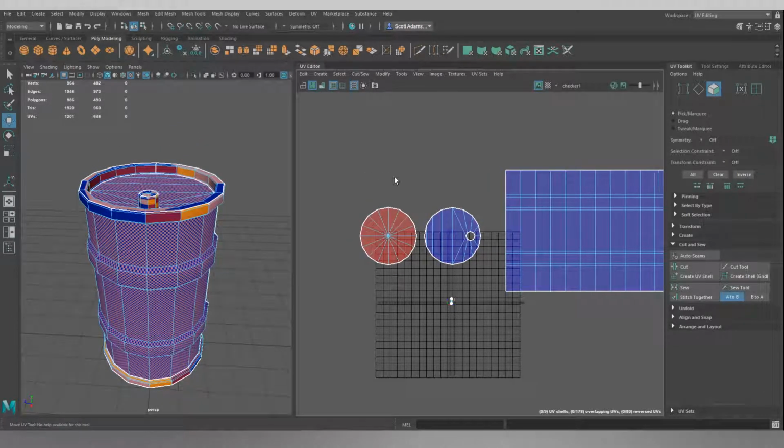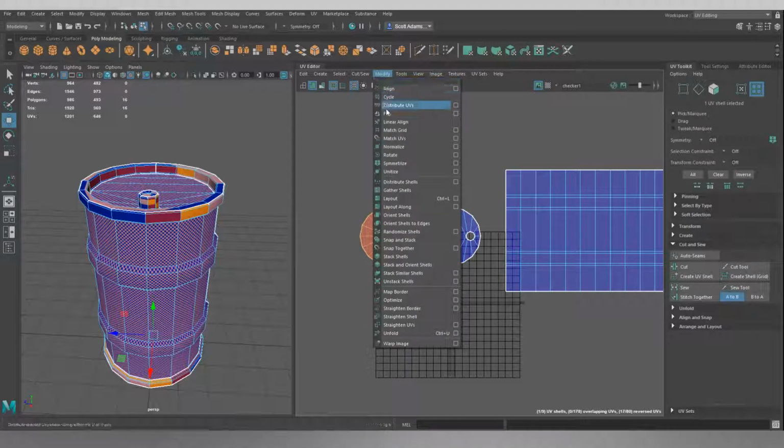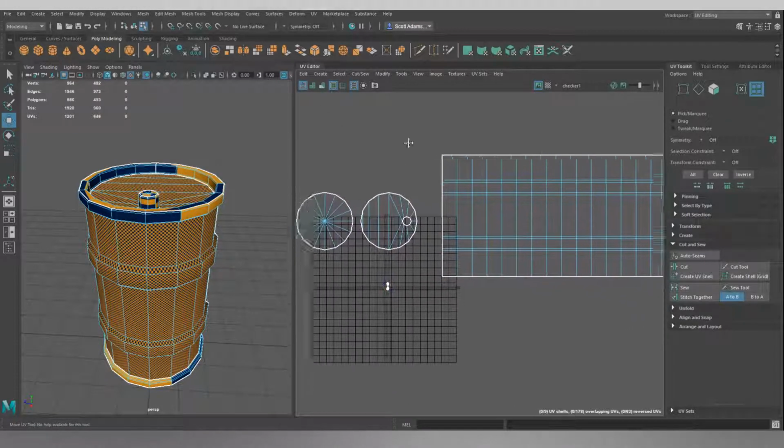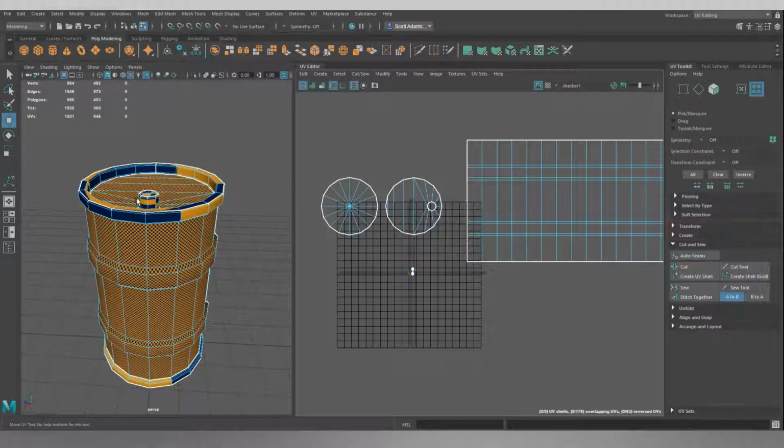So there's a way we fix that. What we do is, we hold right click, we hover over UV shell, we select the bit we want, and we go modify and flip, and that's going to just reverse all these faces back to blue where we want them. So we can click off of this little blue square, so we can just click these little 3 white squares now and bring us back to our normal UV view, and we can move on to the nozzle and